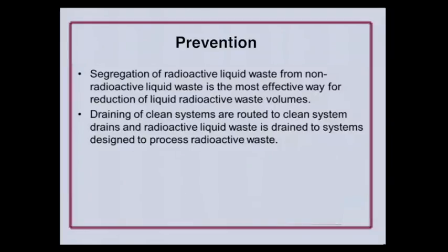And there will be times during maintenance where that has to be drained. What you wind up with is a tendency, if you're not careful, to drain all that clean water down into the radioactive liquid waste system. And you just created that volume of liquid waste. So you've got to think, and the planning and work stages try to help you do that, to where when you drain those clean systems, you drain them to a clean waste system, and you try to minimize contamination and thereby reduce the volume.